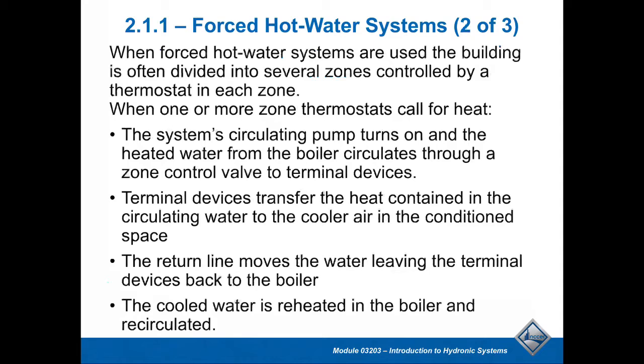Forced water systems are also used in the building, and you would typically see multiple zones. We're not going to see just one zone in most cases. Usually you'll see more than one zone. So when that happens, I'm either going to open up some specific zone control valves and then start a pump or multiple pumps, or I might have multiple pumps and not use zone valves. Typically that's the way it would go.